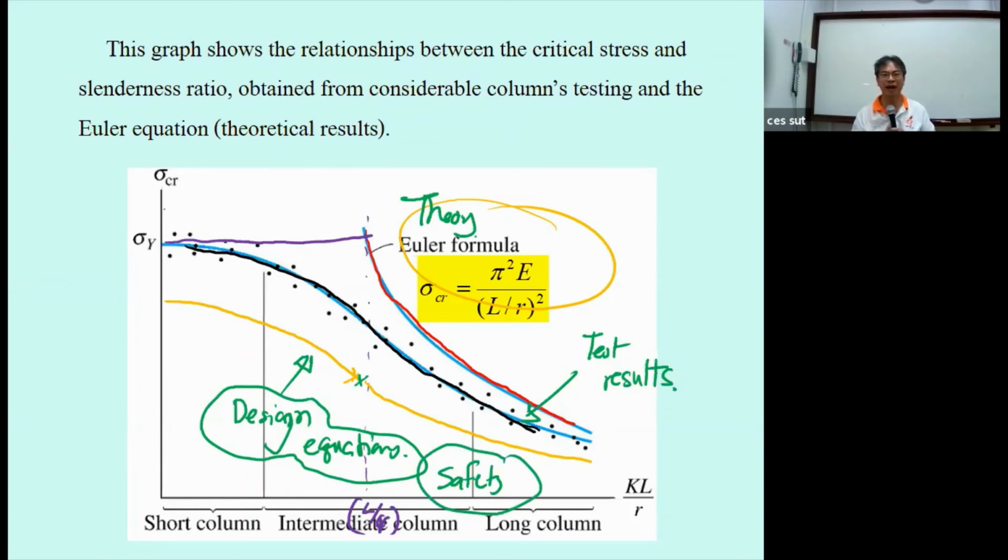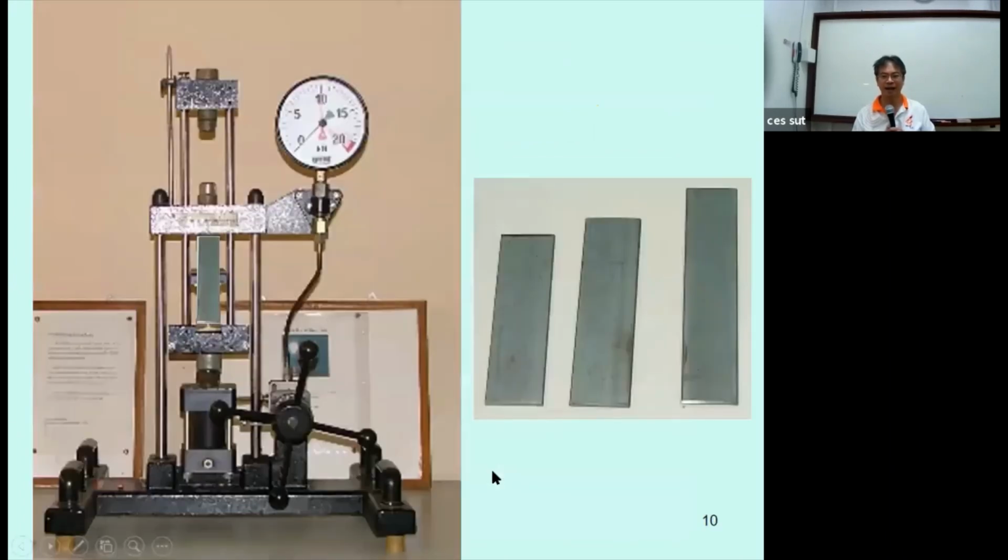Okay, based on this, you can do a lot of testing. You will have a steel plate. We will use this steel plate in the form of a steel column. We will plug this specimen into the 20 kilonewton UTM. After adjusting everything into the vertical direction, you just move the lead needle close to the back needle, and then you apply the loading, increasing it slowly until the column buckles. When it buckles, the lead needle will stay there, so the back needle will come down. And from this you will get P critical.